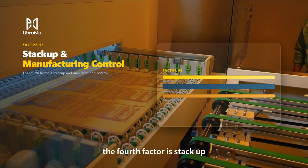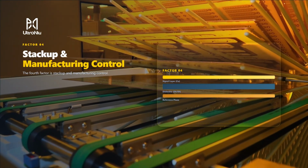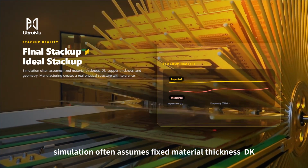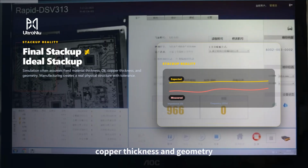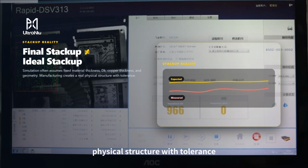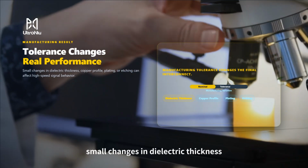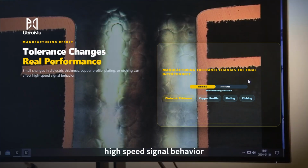The fourth factor is stackup and manufacturing control. Simulation often assumes fixed material thickness, Dk, copper thickness, and geometry. Manufacturing creates a real physical structure with tolerance. Small changes in dielectric thickness, copper profile, plating, or etching can affect high-speed signal behavior.